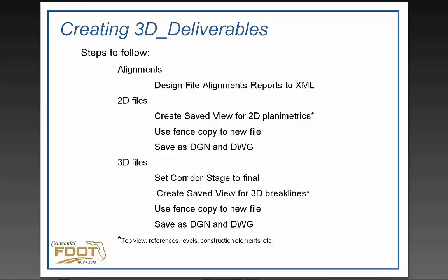I was just going to open up a template and actually show you those. Anything on the top of the surface should have, just like you would see, a curb PM, and they can be the same. For example, all the top points of your curb can use curb PM, but anything that's below the surface, we used a feature called bottom PM. We didn't care if it was below a pavement, a sidewalk, a retaining wall, or a curb. We called every point below the surface bottom PM. That way we could just turn those off at one time.